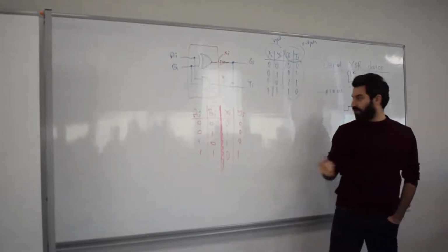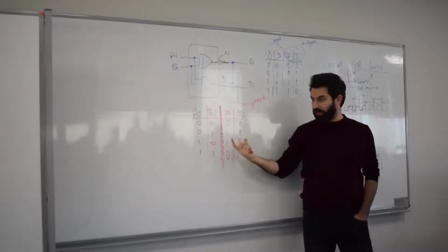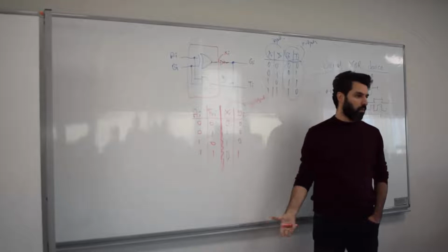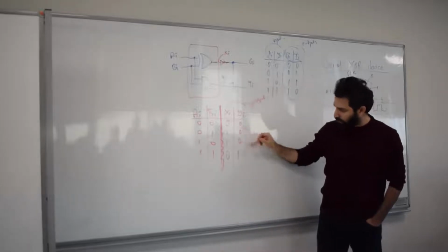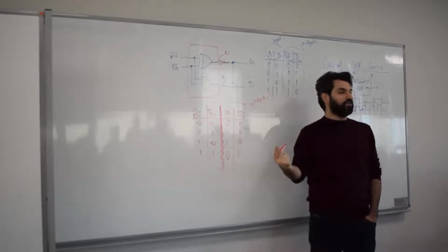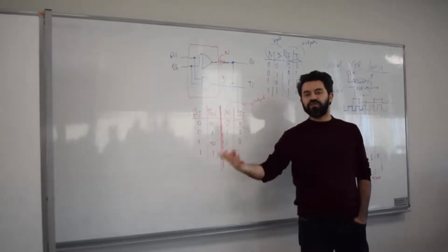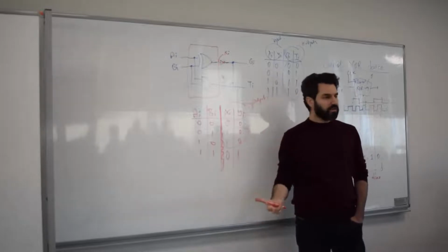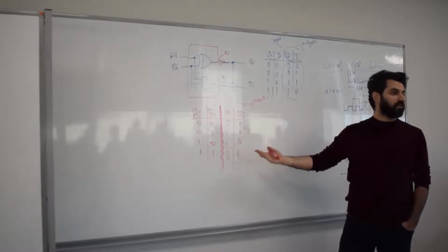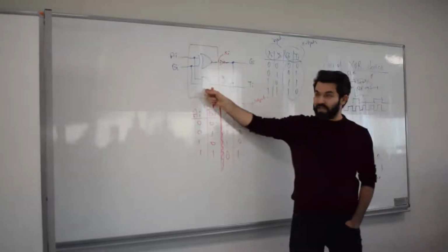By looking at the output, can I uniquely determine the inputs? No. Why? Because I have got two outputs here, 1, 0, 1, 0, that correspond to 0, 1 and 1, 0, two different inputs. That is a violation of the definition of reversibility. So that apparently is not a reversible gate or reversible component or reversible circuit. Therefore, this is not reversible.